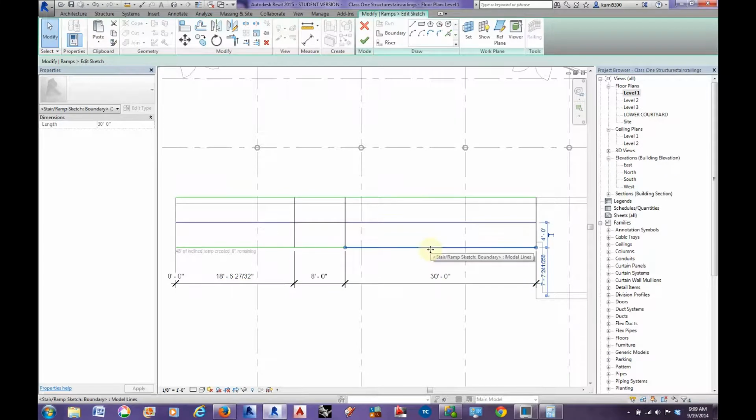You can make custom ramps as well. Again, there's a slope line that you have to be careful of. You have to connect it from each riser point. So this is a riser, this is a riser, this is a riser, and this is a riser. And you want to close your ramp with risers and any landings with risers, but then the boundary lines are the green ones, and you can pretty much make them any shape and it should start to work for you.